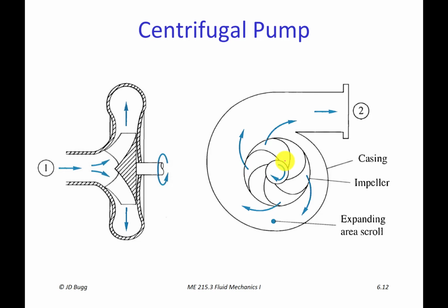This is just an introduction to what they look like. So you can see here why in a centrifugal pump it's actually not that big a deal if the exit is closed off. This impeller spins but the fluid is not in a trapped volume. The pressure isn't going to go to extremely high values. It'll go up to some fairly moderate maximum and just stay there and not really damage anything. If we were to leave it like that for a long time, the fluid in here would certainly heat up, perhaps to dangerous levels. It would take a little while for that to happen.